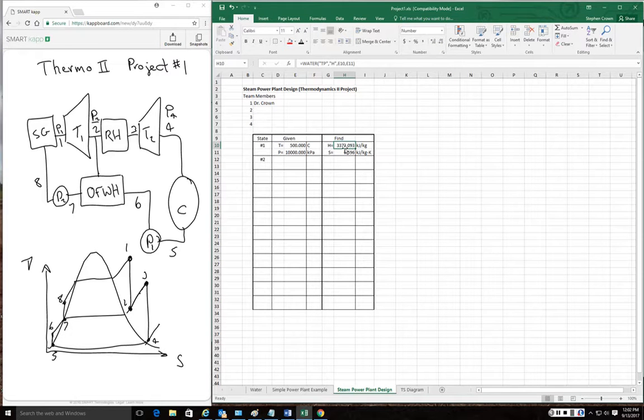And then some fraction of flow that I'm pulling off here, y prime, I can do a quick energy balance there. I know that I want the quality here to be 0. I can find this enthalpy at state 6 from the enthalpy at state 5 plus V delta P, and then I can easily find the enthalpy at state 2, and so I will get that,